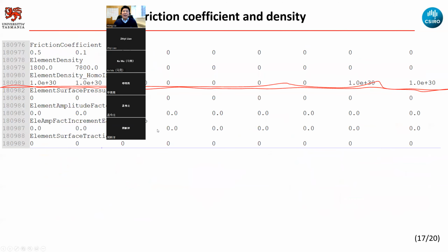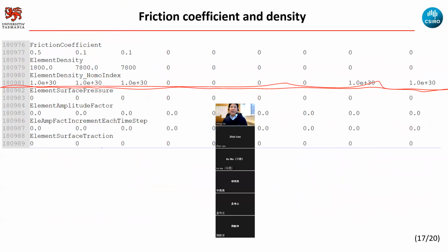Then the remaining parameter is the friction coefficient. This one is different from Mohr-Coulomb. For Mohr-Coulomb, what we are given is a friction angle, which is given for the cohesive element. So after we have the cohesive element fail, what is the residual friction of the surface?